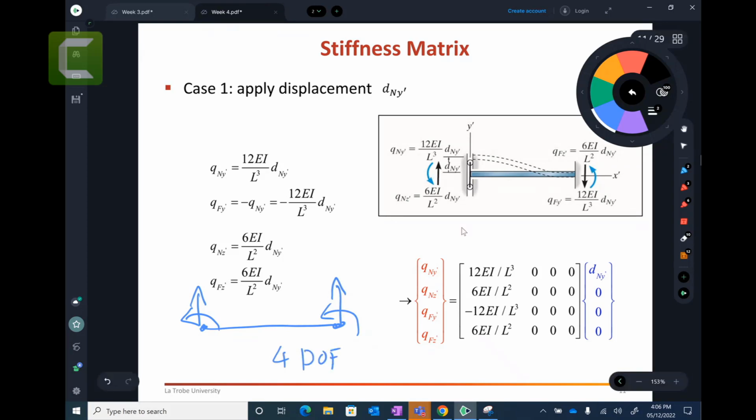Right? Let's make it. So this is the beam element, and this point can go up and down, and it can rotate. This point can go up and down, and this point can rotate. So there are 4 possibilities that I'm talking about for the beam. Now what happens if I fix these ones, and I can also make a slider. Slider meaning like sliding doors. If you have a house, you have a glass sliding door. So it is a slider.